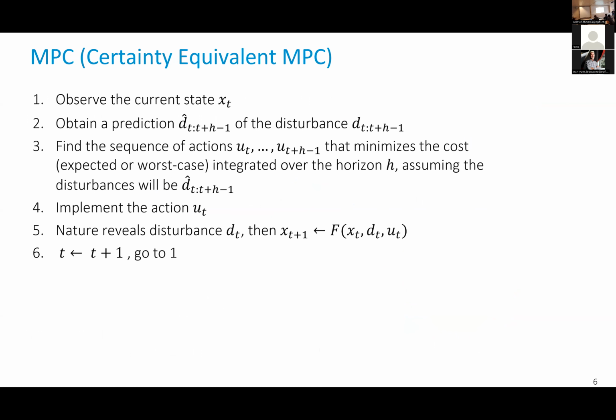How does MPC work? Well, it does the following. We do repeatedly, so every minute, we will need to run an optimization problem and solve it. That's the price to pay. If you compare to affine feedback policy, we computed the affine feedback policy ahead of time. Then we have the parameters. Once the parameters are put in place, implementing the policy is obvious and trivial.